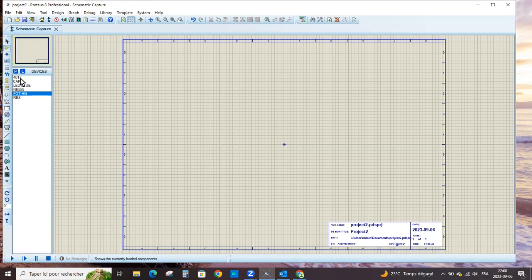So what we want to do now is we click on a part, then we come to the drawing, we click, and we place our part. And we click on a capacitor, and we click once, and let's not click a second time. It's in pink, at least it looks pink to me. If I press on the plus sign, all of a sudden my part rotates. So then I can place it already the way I want.